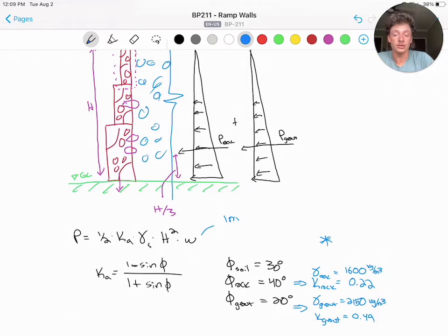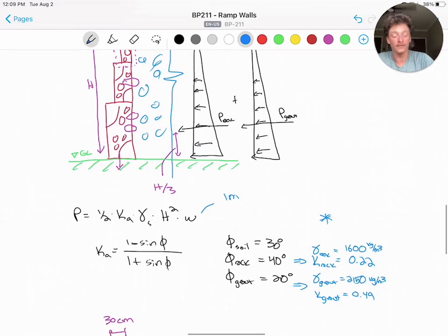So taking the manual assumption that the fill is 85% rock and 15% grout mix, we'll extrapolate that to saying, okay, 100% of the area is the density of rock and 15% of that actually gets filled with grout. And this is applied at 1/3 of the height of the fill, which is the standard point of application for hydrostatic forces.